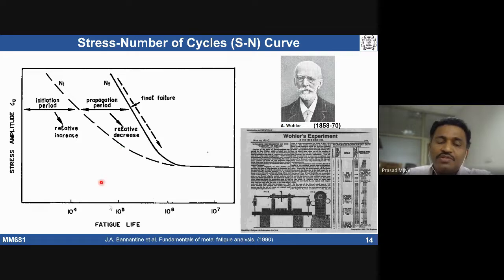There is an important concept called fatigue limit. From the SN curve, people establish the fatigue limit, also called the endurance limit. Usually this is seen in ferrous materials, because most earlier studies were conducted on them. Now, because of the importance of non-ferrous materials like aluminum alloys, fatigue studies have been developed on them too.